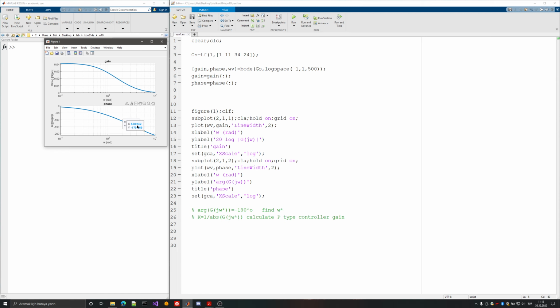So this is 5.803. So hopefully 5.8. A little bit to the right. Just a little bit more. Tad more. There we go. I've caught that point. So the inverse of the y value will give me basically k. You can see the argument -180. This is the argument. I'm looking for -180 degrees. This is this point. And then I have a frequency, and then I'm switching the graphic, and I'm again looking for this value. So this is why we use them vertically, since I can easily look for the same frequency using the other graph. And then I get that it is 0.0028.